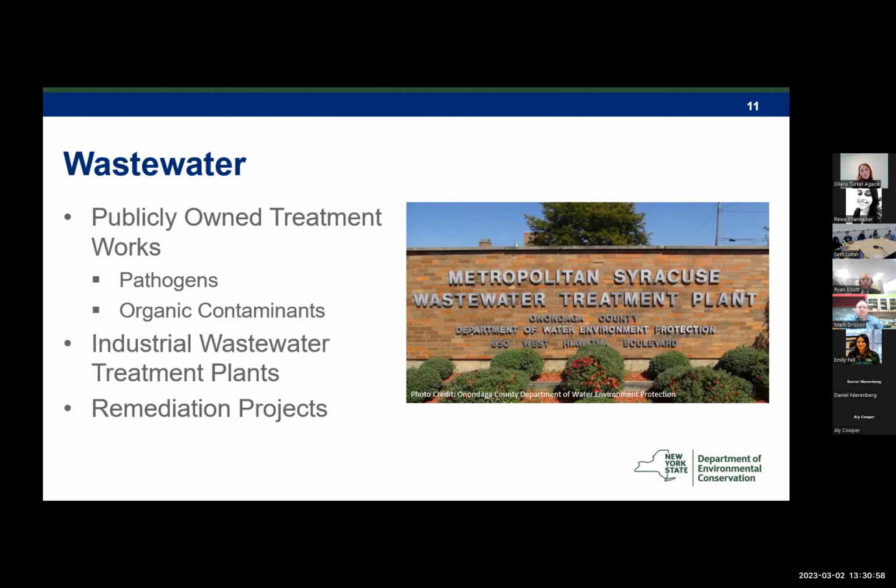And many wastewater treatment facilities in New York, whether due to surface water quality standards or State Pollutant Discharge Elimination System permit requirements, must disinfect their effluent prior to discharging it to a surface water body. When these facilities need to install or replace disinfection treatment technology, which is typically done using chlorination, ozonation, or ultraviolet disinfection, they could consider electron beam treatment as an alternative that would provide an additional benefit of degrading hundreds to thousands of organic compounds.